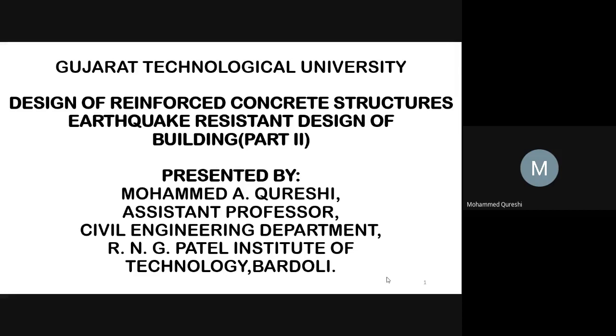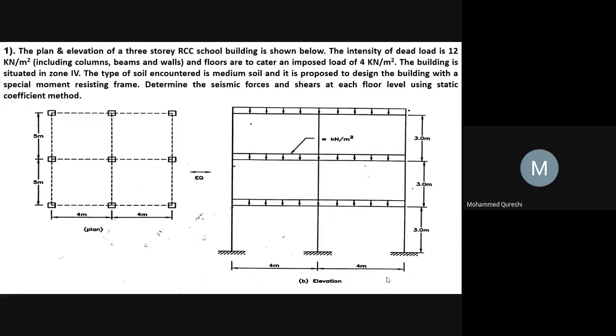In seismic coefficient method, we have to assume that the earthquake forces are static in nature and we consider only static condition, means the forces do not vary with time, and the seismic forces are lateral forces which act from any orthogonal direction. So we will solve the first example related to seismic coefficient method.